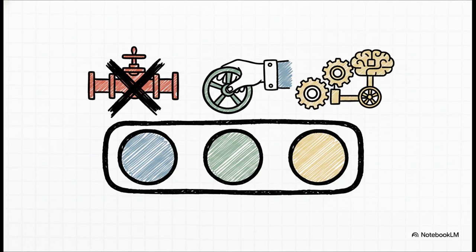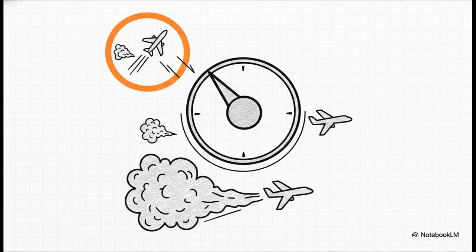Moving over to your pack controls, you're going to use the OMA trick. That's OMA for off, man, and auto. Off simply shuts the air cycle machine down. But switch it over to man or auto, and you begin supplying conditioned air while modulating the bypass valve. Right next to that is your bleed control. For bleed airflow, you've got to remember the MMM rule: min, norm, max. And here is a huge takeaway. You can never, ever forget that min is the absolute only selection permitted for takeoff. Norm and max are great for modulating flow during other phases of flight, but for takeoff, min is the law.